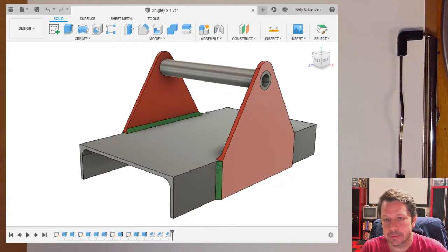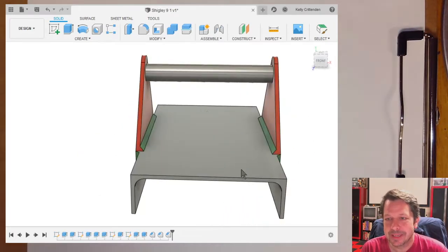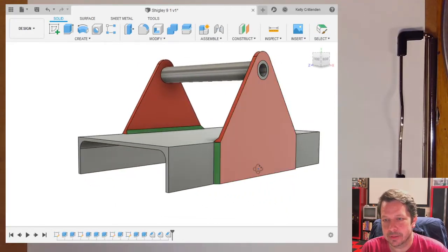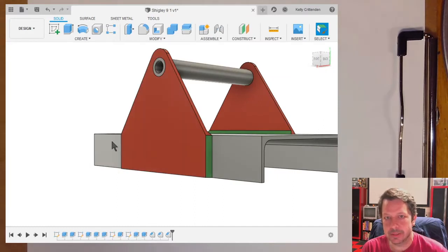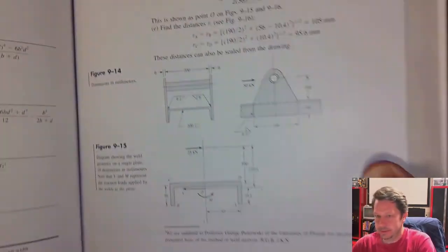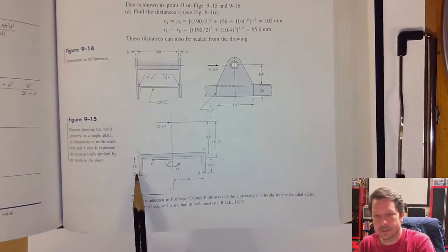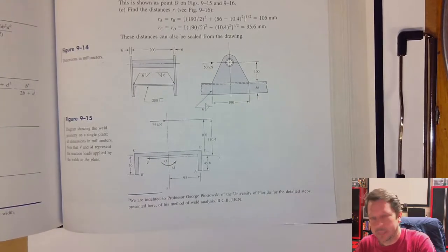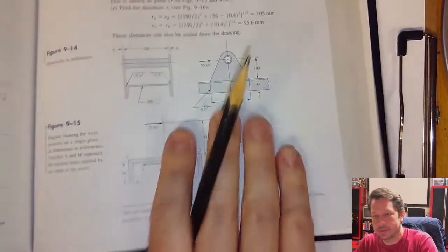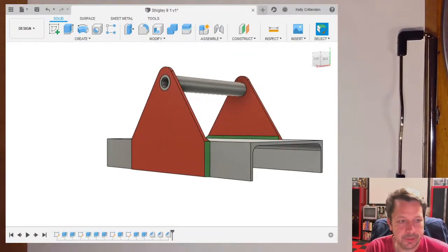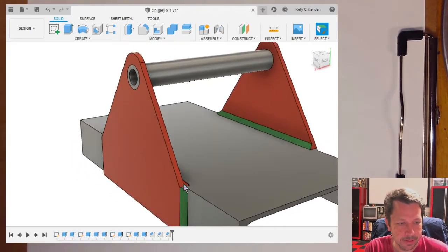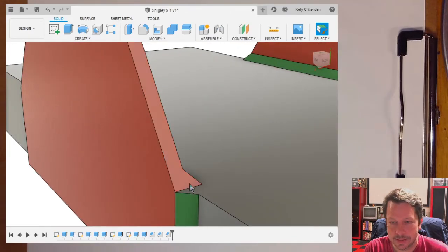Your book does group them into this weld on the top and the weld on the side and the side. It groups them into one C shape. That's what this is down here. Those are those 3 welds put together. And so, this corner over here kind of gets weird, because when you look at what's really going on, it doesn't even really show up too well in here. So there would be some welding that goes across this little gap right here to connect them together.